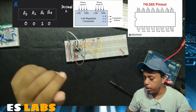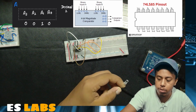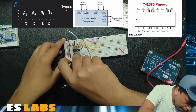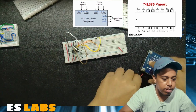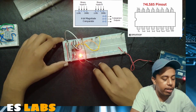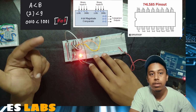So what we simply do is go to pin 5, pin 6 and pin 7 and measure the voltage there. Alternatively, we can also test the output via LEDs. Now I am powering this circuit. The LED present at pin 7 is glowing, representing that A is less than B, because our A was 2 and B was 9.